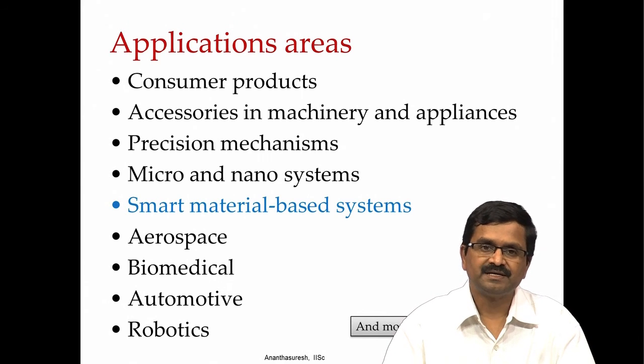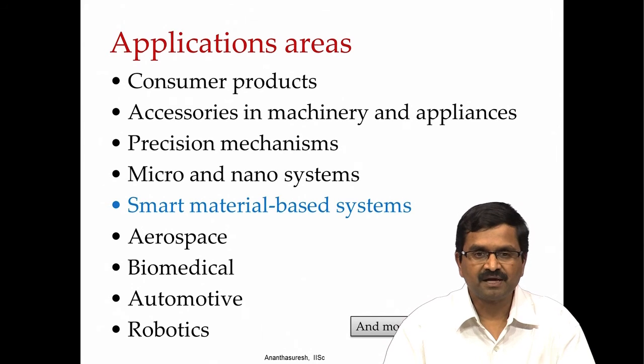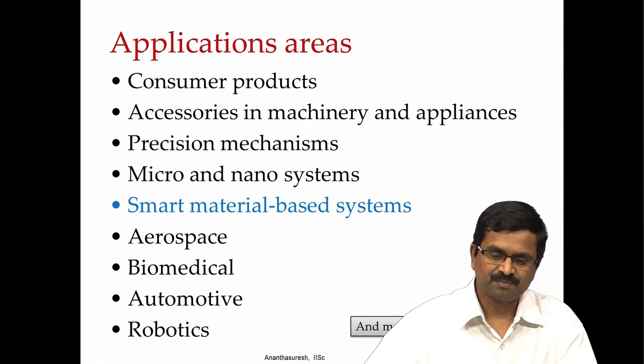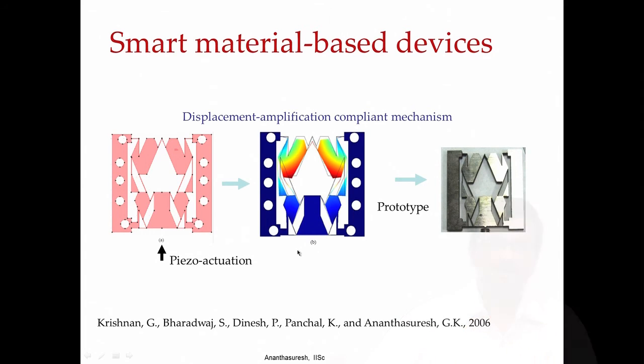So, you need a mechanism to convert that large force and small displacement to large displacement against some smaller load. And one such application that we had worked on, a number of people have worked on using compliant mechanisms for piezoelectric materials, electrostrictive materials and shape memory alloy materials and a number of others.